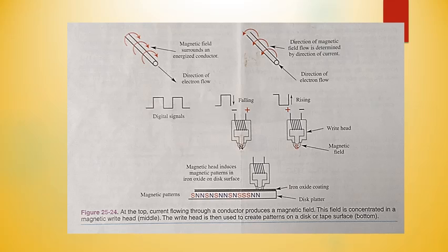A hard disk drive is very simple in construction. It contains one or more platters that are coated with a special iron oxide. The iron oxide retains magnetism induced by the read-write head attached to the end of the actuator arm. The magnetic patterns are in response to digital pulses sent to the read-write head from the computer motherboard and CPU. The digital pulses represent computer data.